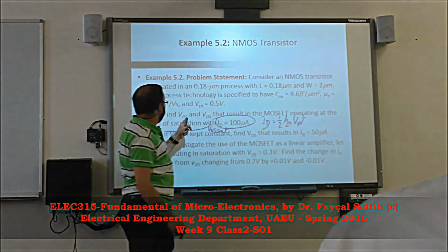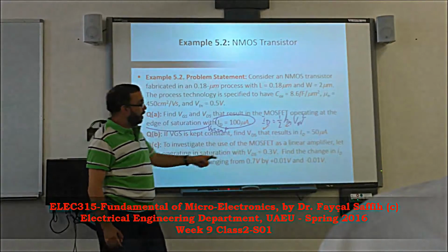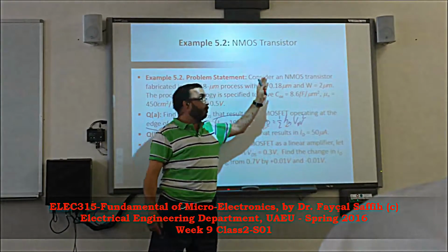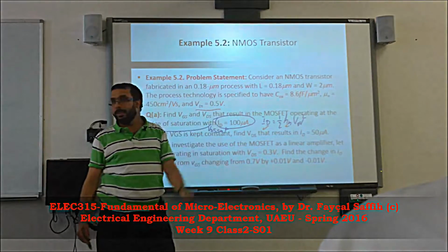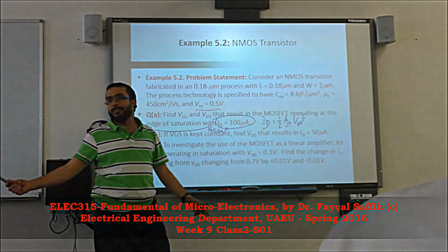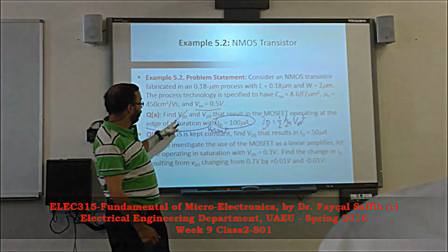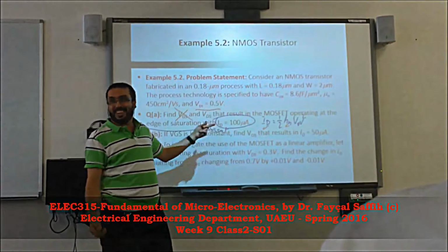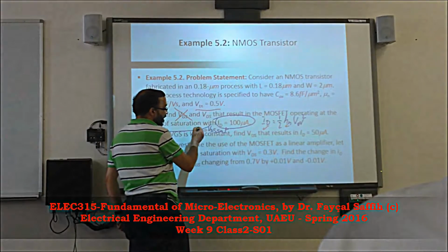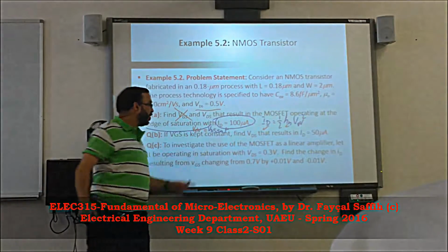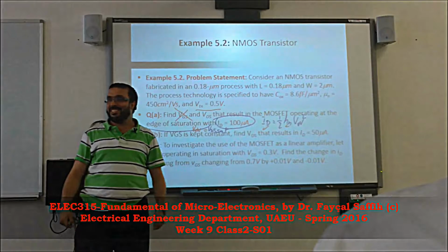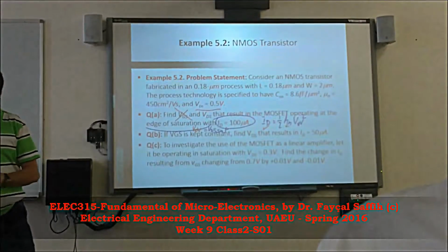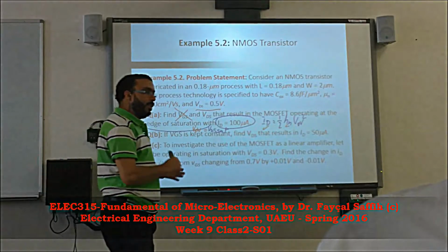And the question is what? VGS. Oh, very much. We have a relation between overdrive and VGS. All I did was this plus VT. What's VT? Is that VT? Yes. That's it. So we're done. Good. So VGS is solved. Now VDS is equal to what? VOV. That's it. This is my VOV, the overdrive, because I'm at the edge. Finish. Right, Tanya? Excellent.